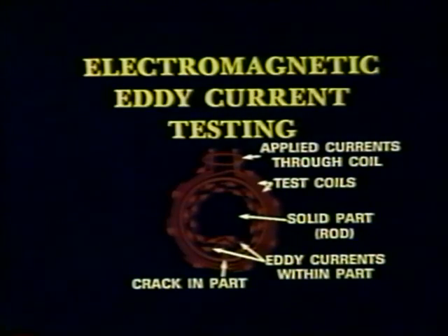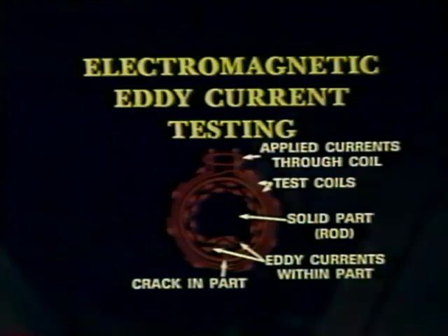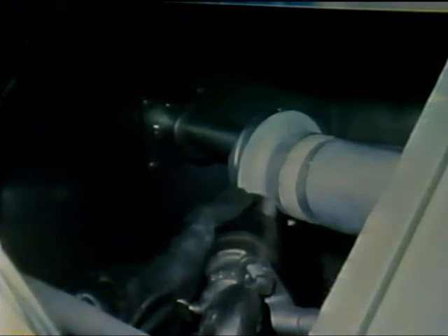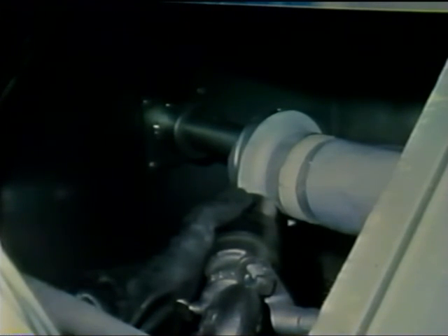Eddy current inspection is used in critical areas of the blade. This procedure is now required by an airworthiness directive on several models of propeller blades. Shot peening is a process that uses hardened steel balls shot from a pneumatic gun against the propeller blade. This is used in the shank area of the blade to ensure maximum strength of the surface of this dynamically stressed component section.